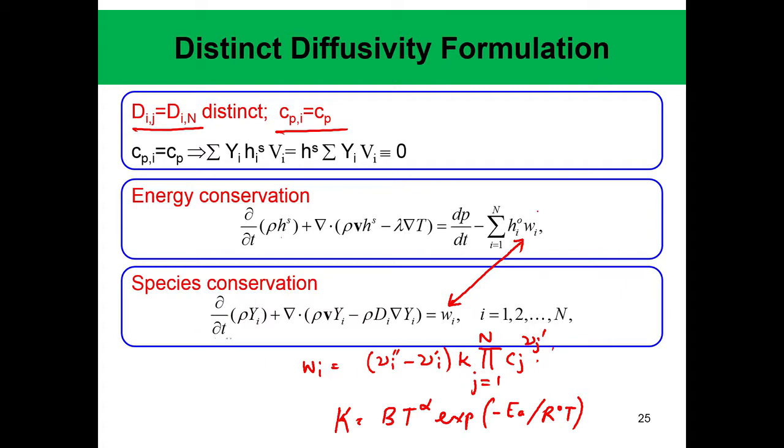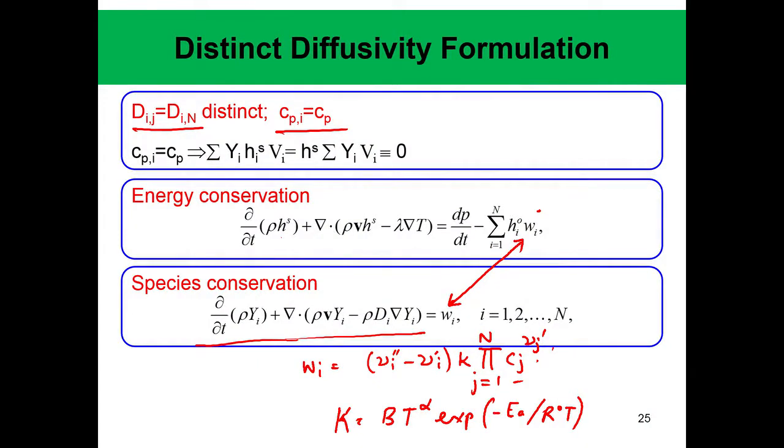So, even though it is not apparent where temperature arises, of course the temperature comes through here, right. The reaction rate constant contains temperature, so that affects changes in the species mass fraction, and of course temperature changes density also, and then this also changes here. Cj is essentially a species concentration, and we can write this Cj in terms of mass fraction. So, the energy conservation, the sensible enthalpy, actually couples with the species equation through this law of mass action term, right.